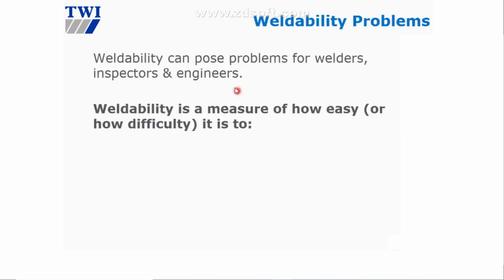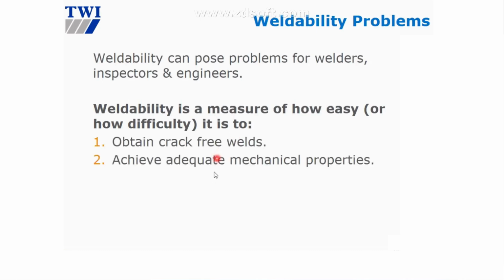So weldability can pose problems for the welder, inspector, and engineer. Weldability is a measure of how easy or difficult it is to obtain a crack-free weld, and also achieve adequate mechanical properties in terms of tensile, hardness, toughness, and ductility. So that is mechanical properties.